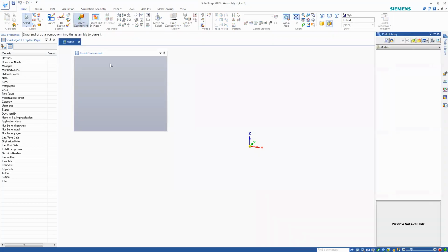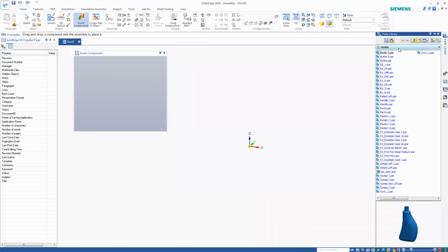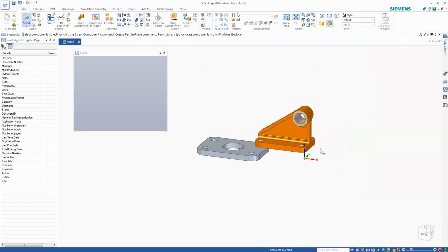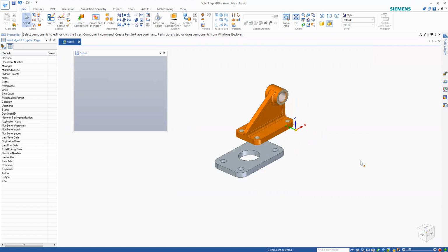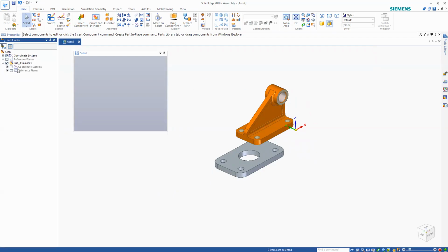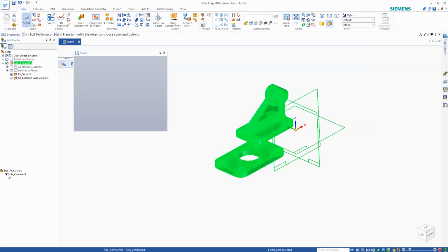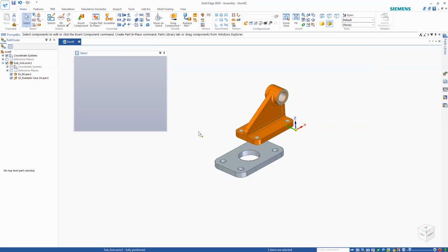And then you go to insert component. Say it's in the model, I said sub-assembly, right? You see here, sub-assembly, and then you can drag it and place it over here. That is the sub-assembly. This whole thing is usually recognized as a sub-assembly, and inside that one you have some other parts, right? The moment you select this one, it's already fixed, it's already grounded. Now moving parts relative to each other is a different issue.